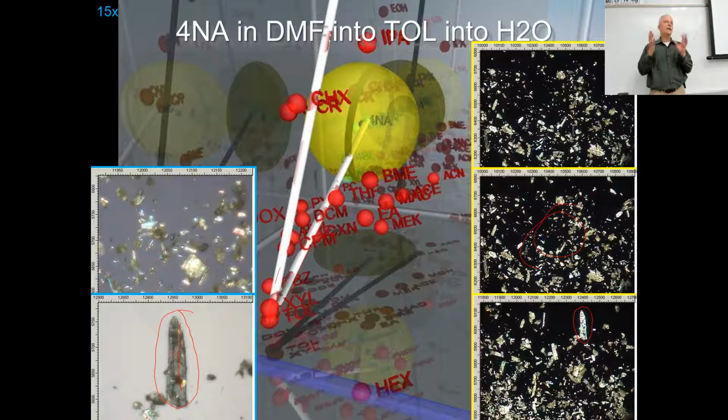These are the things that engineers do to get the right crystal structure: stir rate, pressure, temperature, volume. And if they're getting different results and they didn't know that they changed out the glass impeller with the Teflon one, they might get totally different crystal habits and not understand what changed, because all the dials on the control panel are the same.